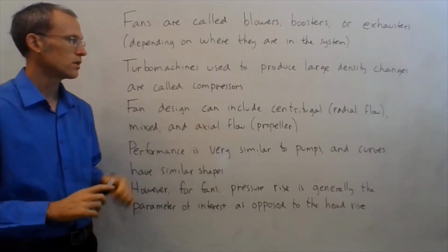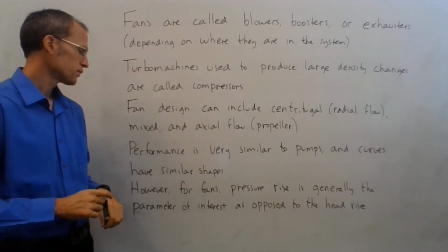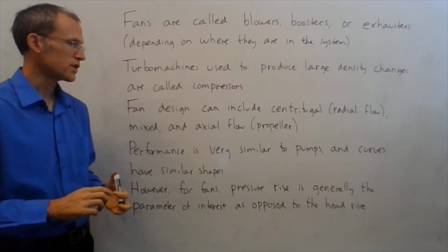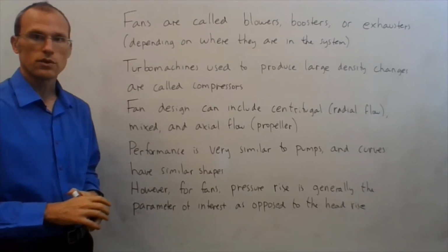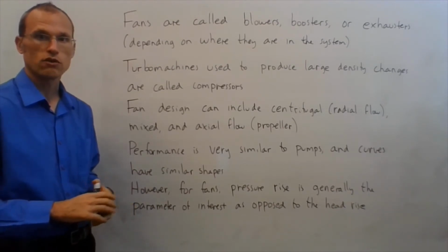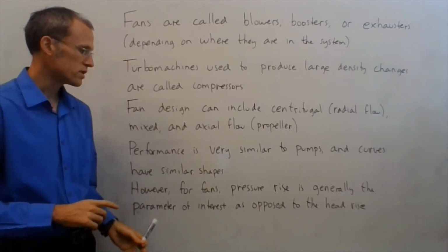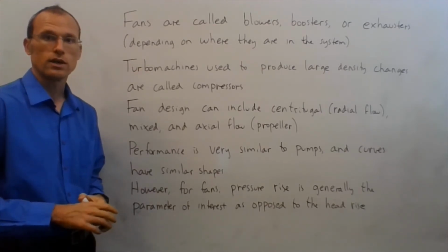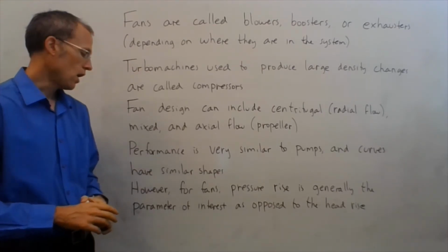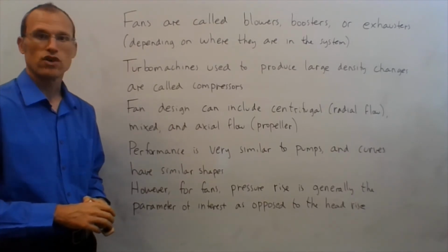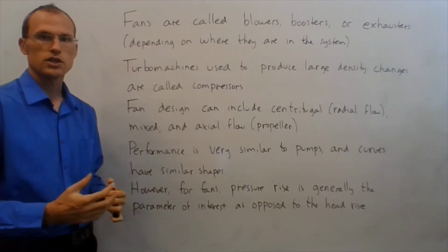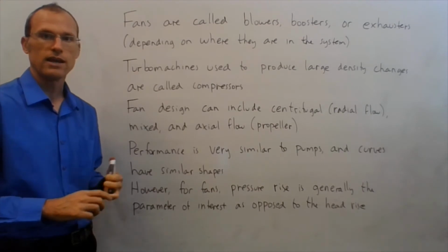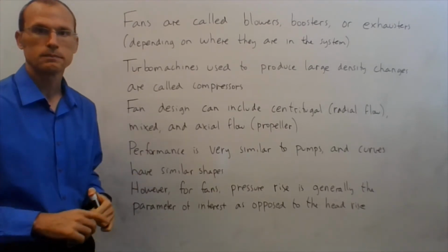So the axial flow fans are also called propellers. And the performance curves are very similar to the pumps. So the shapes that we saw for the pumps, the curves look very similar. The one difference here is that for the pumps, for liquids, we generally deal with head rise or head loss. For the fans, we deal with pressure rise. Just easier to deal with, head for liquids and pressure for gases.